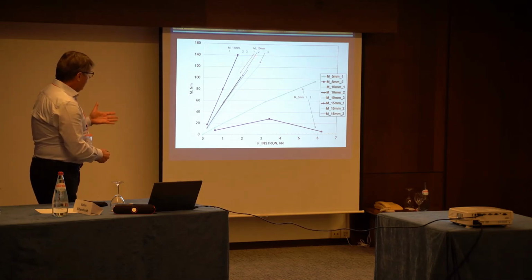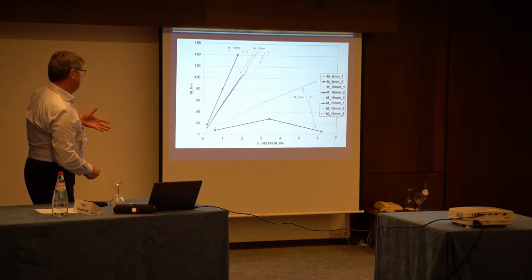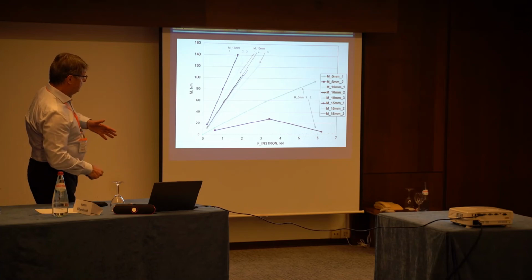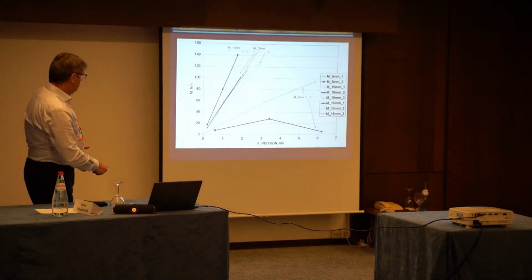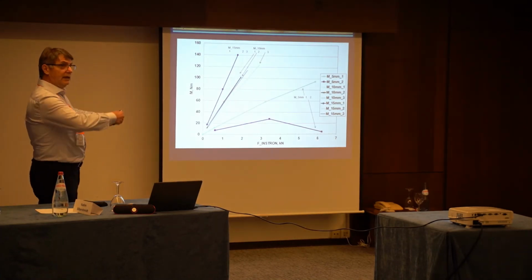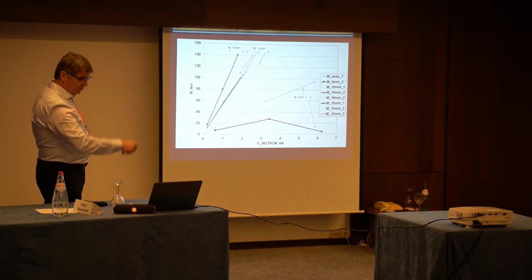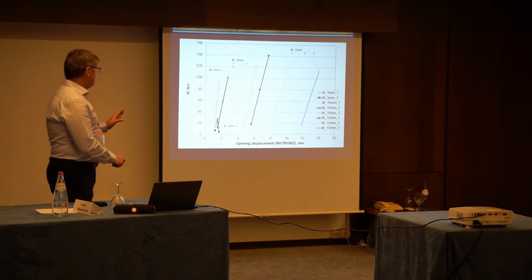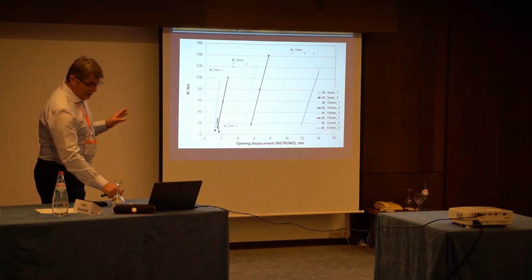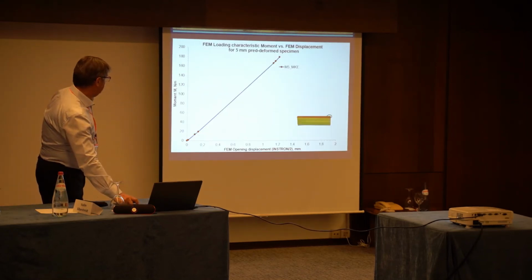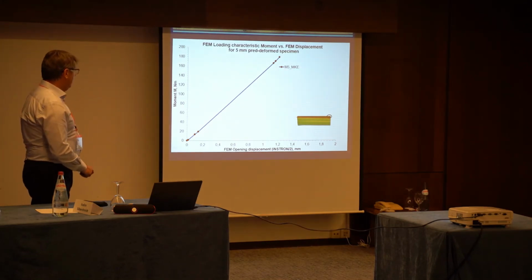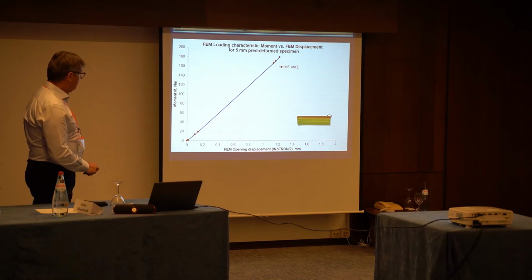We did this also for 10 millimeters and for 5 millimeters, where we have only two loading cycles. First one, and then when you repeat the second, it's almost flat, your bending moment decreases because the tensile force decreases. It becomes more flat. So now with this displacement we want to calculate how it behaves, and now I'm going to present the model. This is what we have in the moment, and this is what we have from the finite element computation.